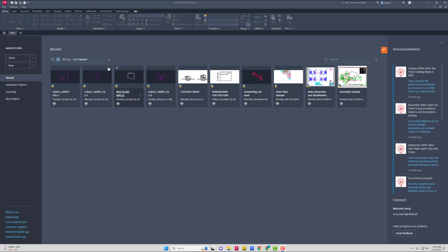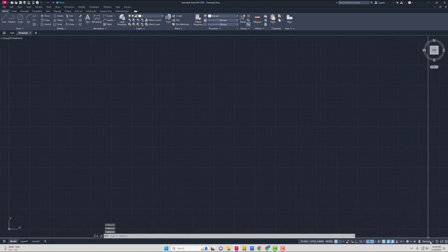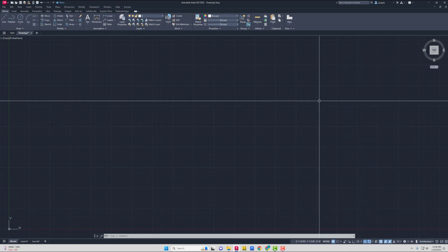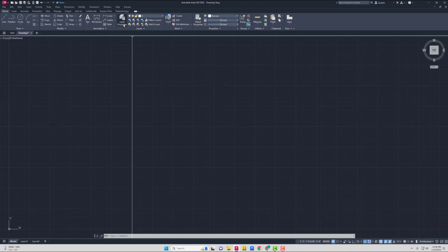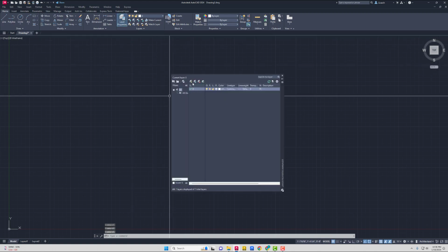So what I'm going to do first is start a brand new AutoCAD drawing. And I want to make sure that my units is set for architectural, just to kind of get into the practice of doing that. Then I want to create a new layer. So I don't want to be on layer 0. I'm going to click the stack of papers with a yellow starburst. I don't know what you call that, but if I click that now, it creates a new layer for me.